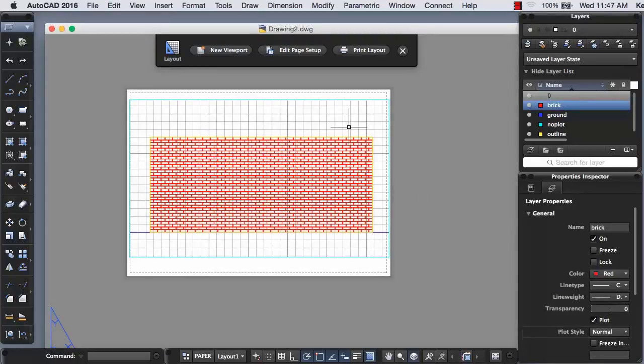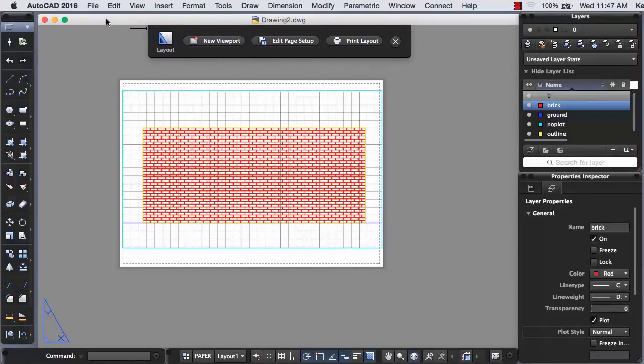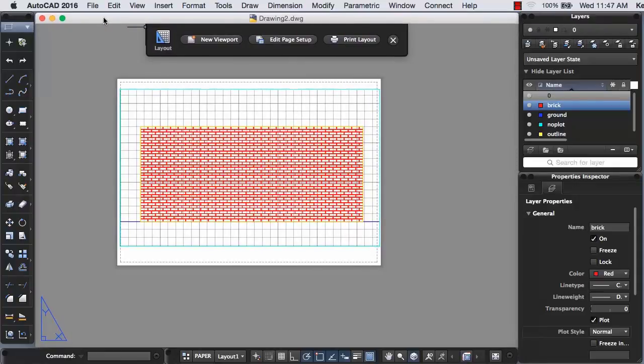Okay, so I'm back. I did have to save it and reopen it. It's a glitch that I noticed with you guys yesterday. Not with you guys, with the software. But because I had copied and pasted it into the new template, it would not give me access to those plot styles that I was looking for. So I had to save it, close AutoCAD, reopen it. That's all I've done is reopened it, come right to here, and now my style 1 is available. It's irritating, I know, but that's what it is.